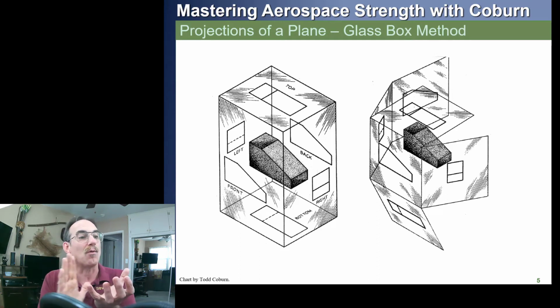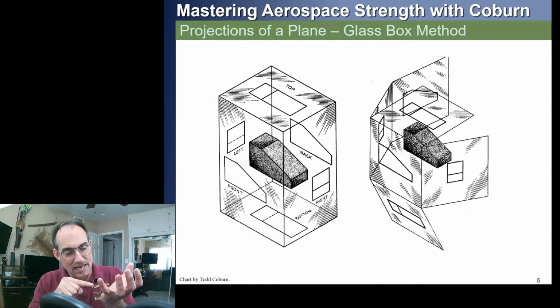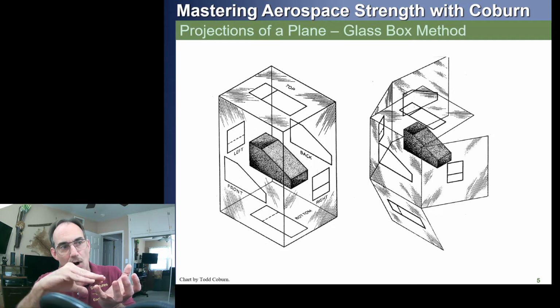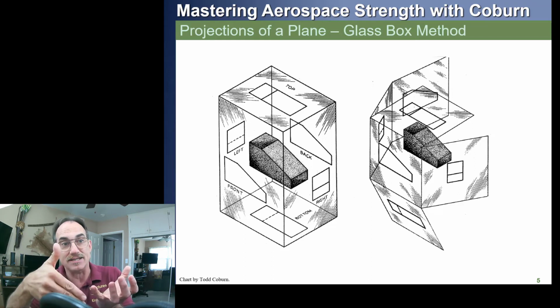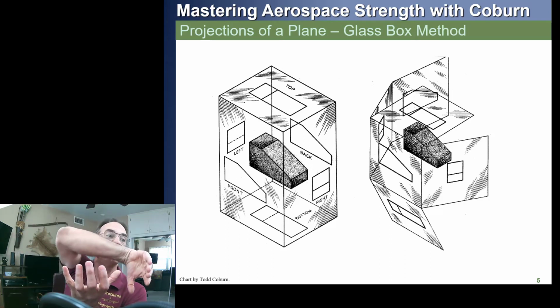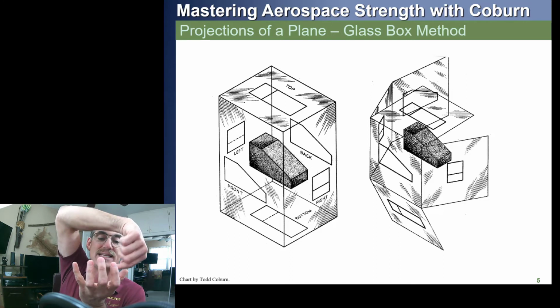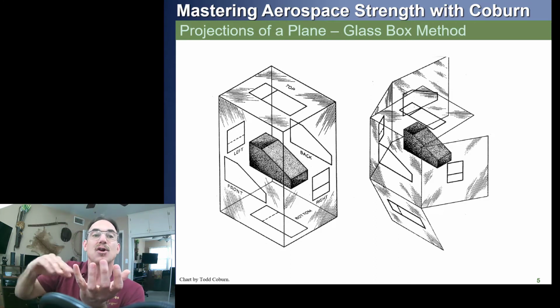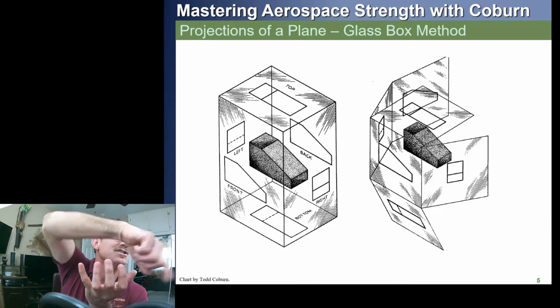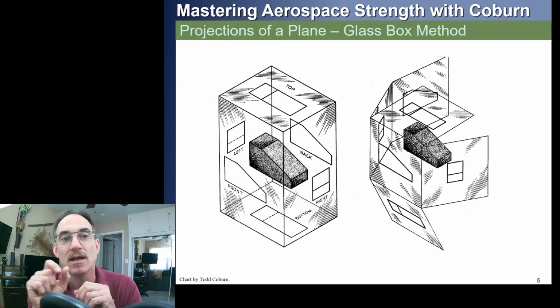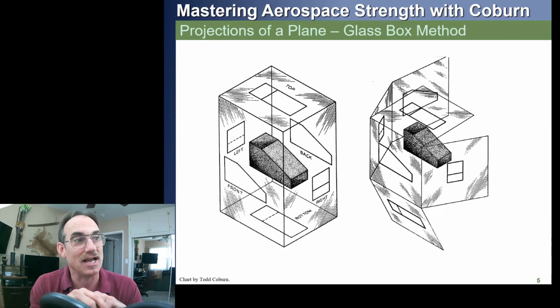You'll notice on the right view, we can see the lower edge of the part, the middle edge where the part creases, which is shown as a solid, and the top of the part, and the two sides. If you go around to the left side, you'll notice you can see the top, the bottom, and the two sides, but the other crease line is on the other side. You can't see it directly, so we show that as a hidden line, which means a dashed line.